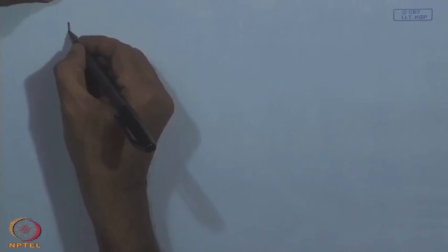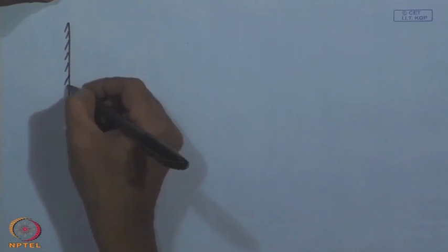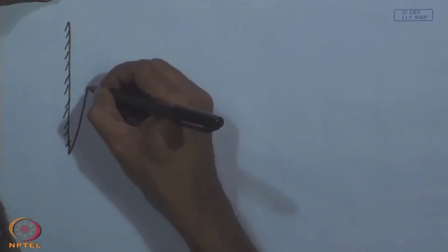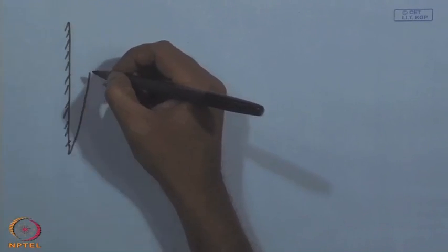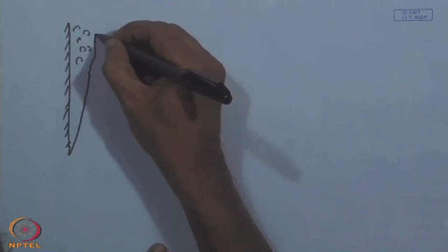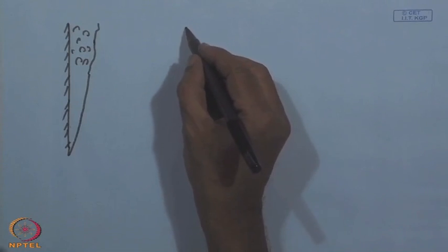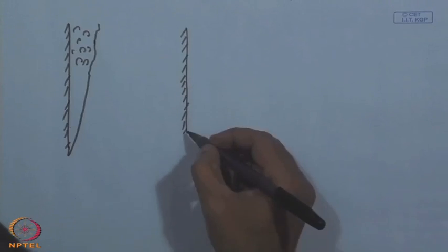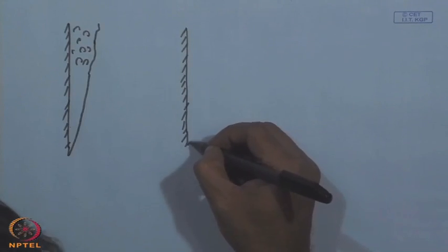Lastly, I want to say another thing, that the analysis which I have done has a lot of limitations. We are assuming that the vapor film is laminar, but after a certain distance the vapor film becomes turbulent, so for this portion the turbulent analysis is important. Then in many cases we have assumed a smooth interface, but it is not like this.